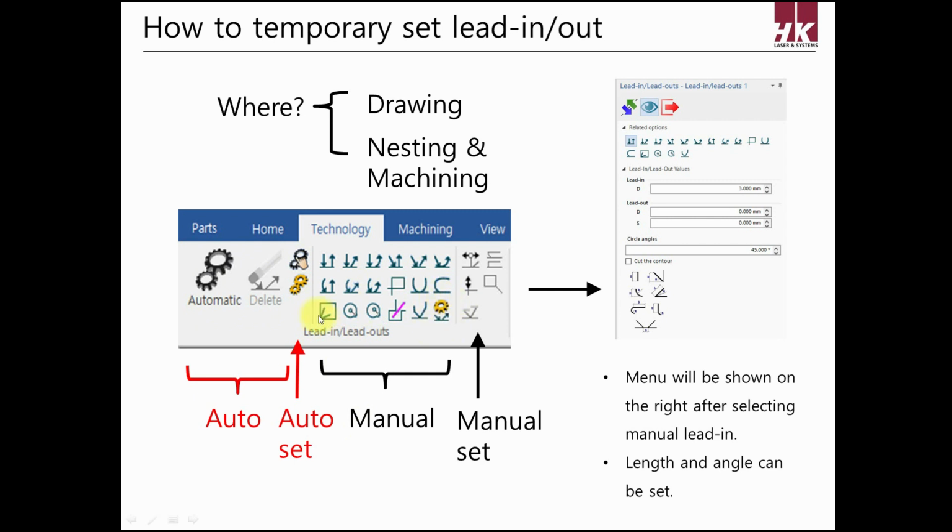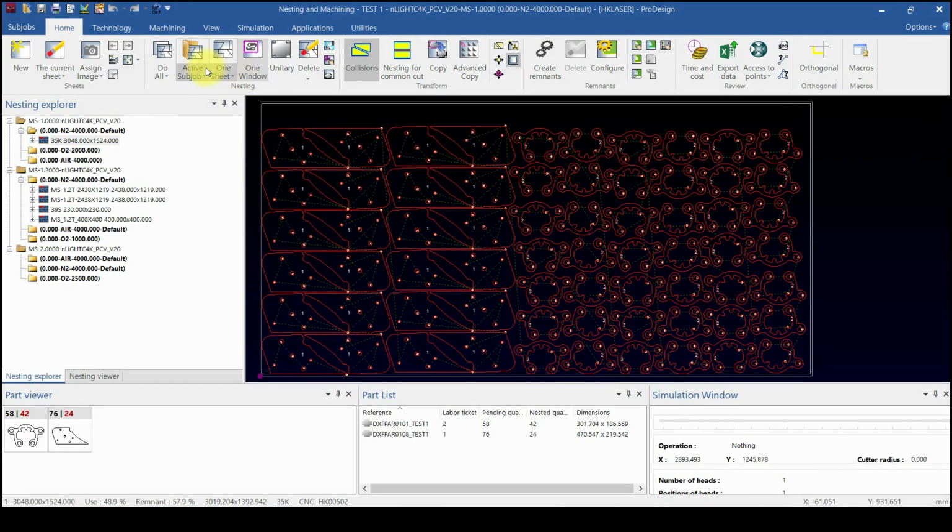The first yellow wheel-shaped icon is configuration. The second wheel-shaped icon is automatic configuration. From LANTEK version 40, lead-in length and setting can be set directly just by choosing the lead-in type without using normal setting. Now, let's try to apply the position of automatic lead-in and manual lead-in.